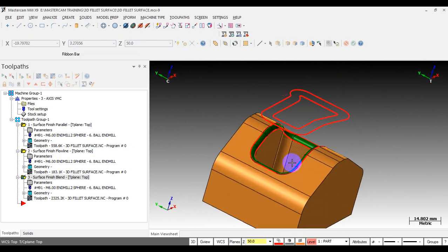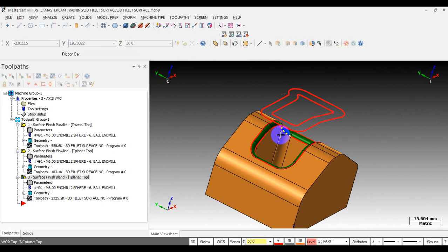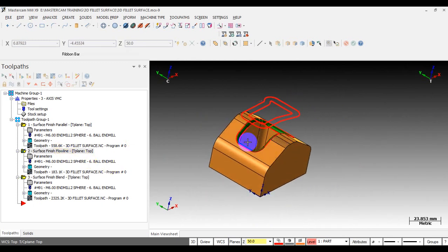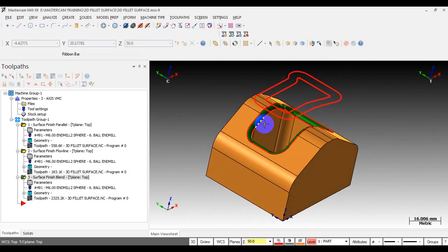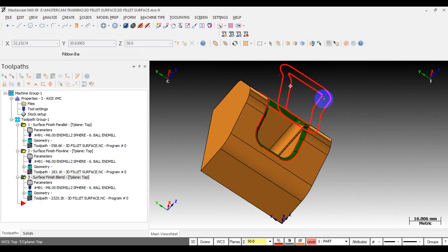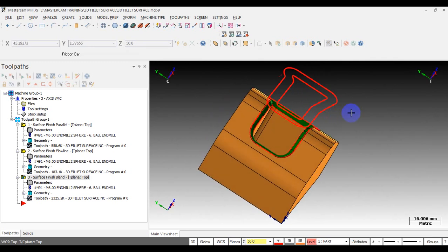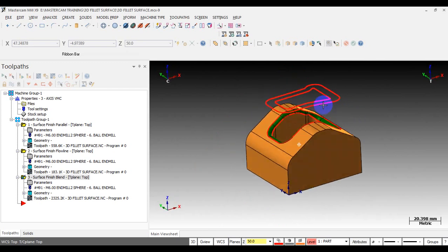Two kinds of toolpath that we can use to machine a fillet surface like this. The first is the Flowline, a very simple but very effective toolpath. The second is the finish plane toolpath. In the finish plane toolpath, you must take into account the plane curve because that's very important. It will limit the tool motion. So you need to make some trick with the steep surface. If you don't, the tool cannot make a complete cut on the steep surface. Okay, thank you for watching.